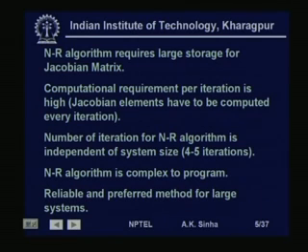It is a very reliable and accurate method, and therefore is the preferred method for large system power flow applications. Most commercial programs for power flow use the Newton-Raphson algorithm, and people have solved problems of more than 10 to 20,000 buses using it.